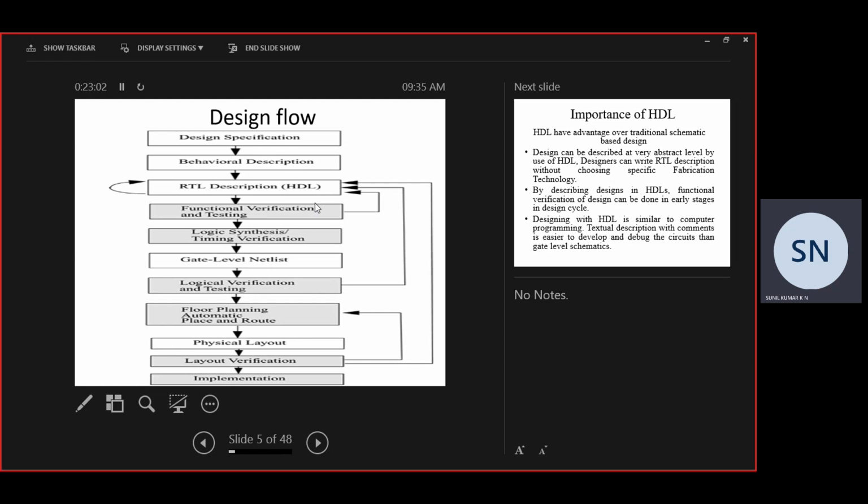On state, since it is connected to VDD, you will be getting output as VDD, which in terms of logic level is 1. This 1 is being given as input for both these two. Since it is 1, this will be off. Since it is 1, it drives this transistor because it will be on. Since it is connected to ground, the output will be 0. So that means when I am giving A and B as 0, I am getting output as 0.